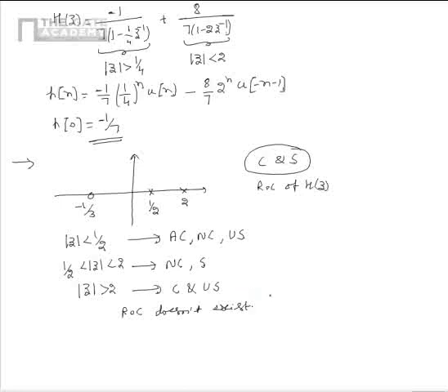Now, let us consider another problem as per which the system function of an LTI system is given as H(z) = 2 / ((1 - 2z^-1)(1 - 3z^-1)). We need to find the LCCDE that represents the LTI system.